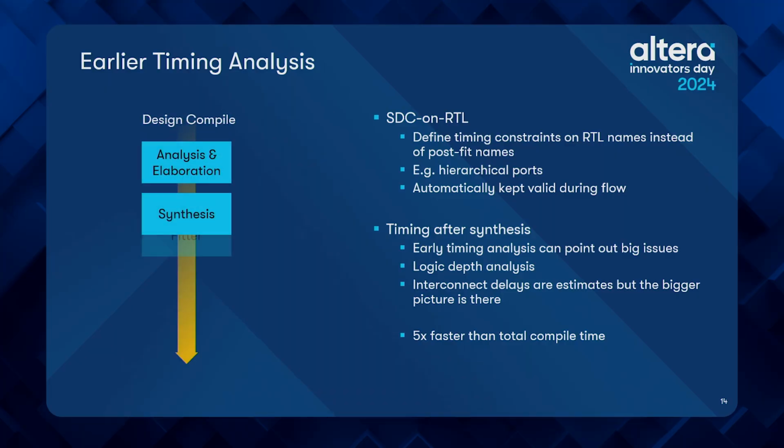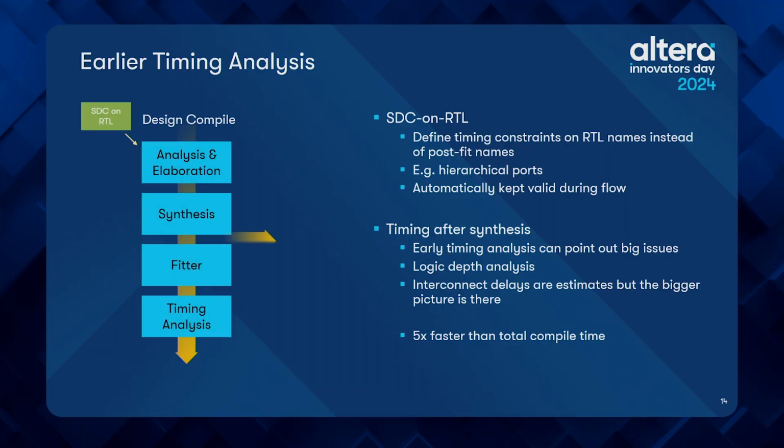So moving on to timing analysis, earlier timing analysis. There's two parts to this. First, you can now specify your SDC constraints on the RTL. Traditionally, in Quartus, you had to specify your SDC constraints on the post-fit names.